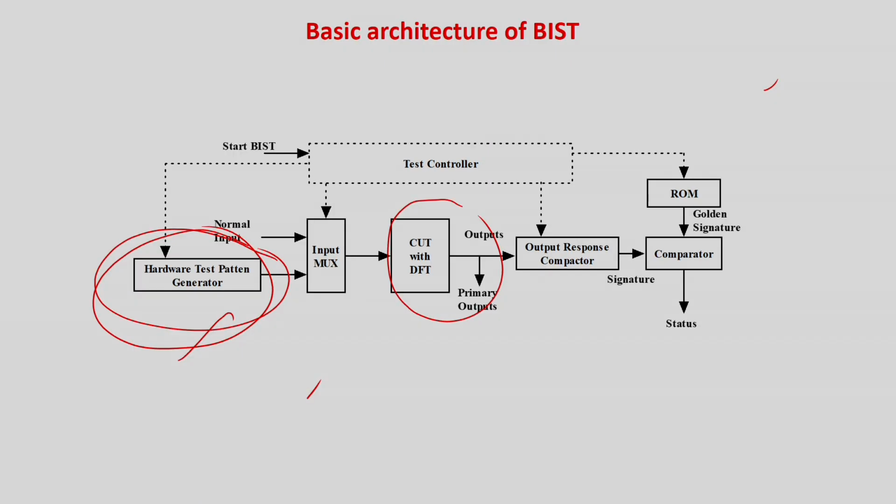That is the philosophy. If I don't have a BIST, I cannot test my circuit before startup. But if I have a built-in test, even if it's a very small part of the original test which you do in offline ATE, I can still apply it with a very low hardware area overhead for the test pattern generator and the response analyzer with compaction. Some level of confidence can be obtained if I have a BIST, so more reliability can be given. And research has shown that you can very easily have very good compaction schemes so that the aliasing is less.